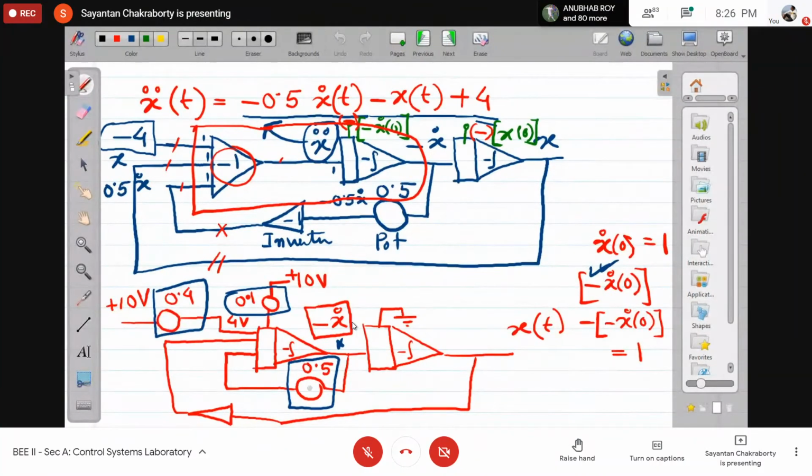So this port setting will be 1. This will be 1.25. This will be 0.98. And there will be another port 0.98. I'll leave it to you to obtain this. And say the initial conditions, both initial conditions are 0. Okay. So there will be simulation like this.